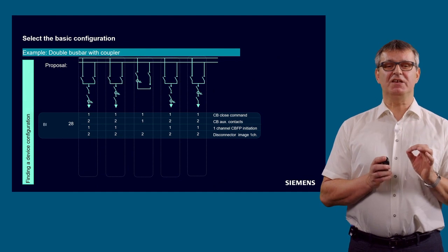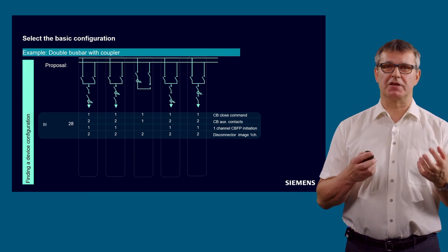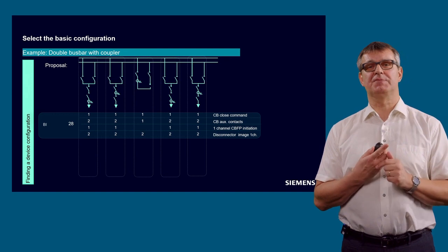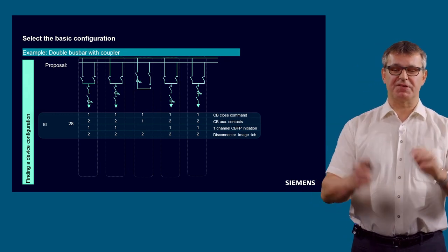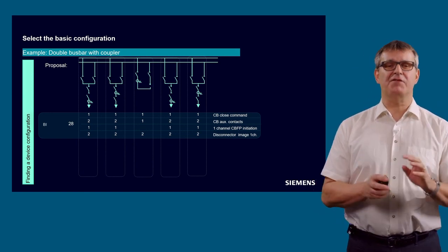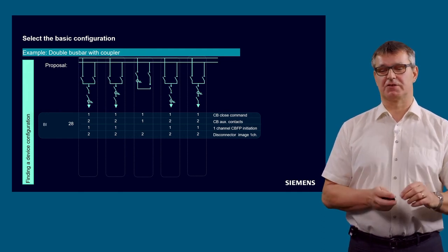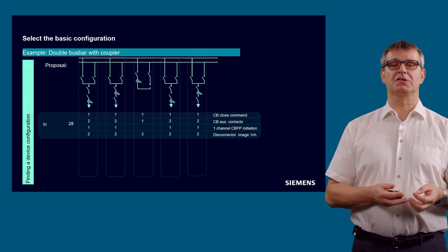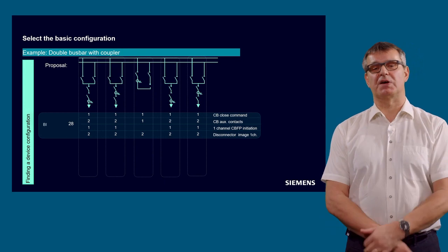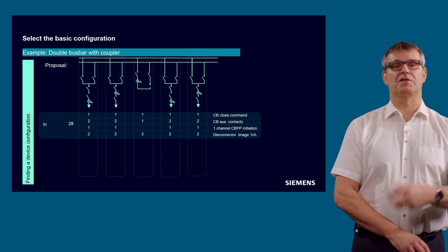So if there is any wrong tripping of the busbar protection, typically, as a PLM for busbar protection, 1 or 2 times a year there's a high upset in our organization about wrong tripping of a busbar protection. And nearly every time the reason was that they forgot they have end-fault protection, they have an external fault, they have an automatic reclosing, and they forgot to use the CB close command, and you have a wrong tripping of the busbar protection because the end-fault protection was deactivated too late because of the missing CB close command.